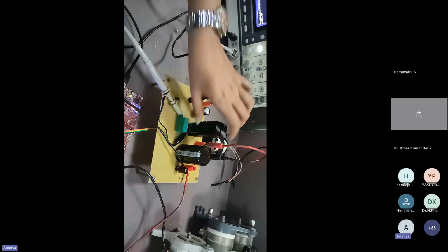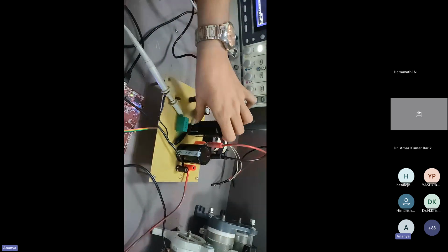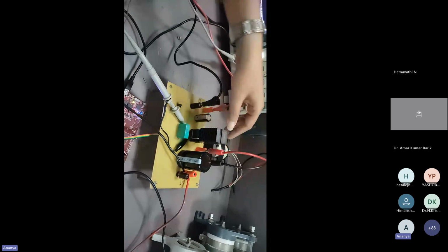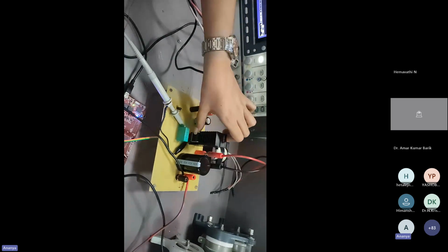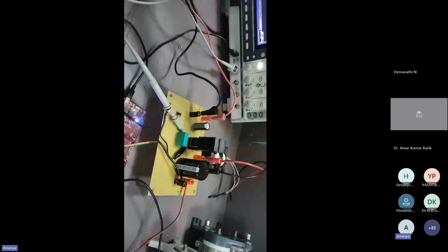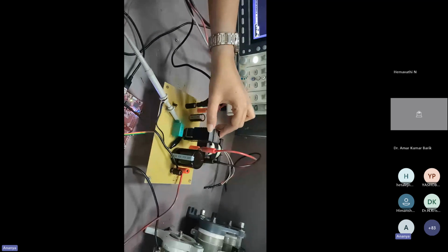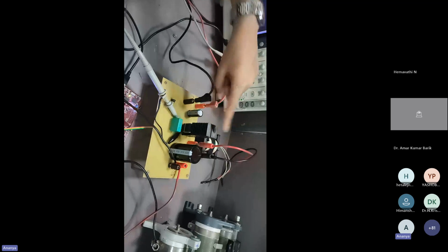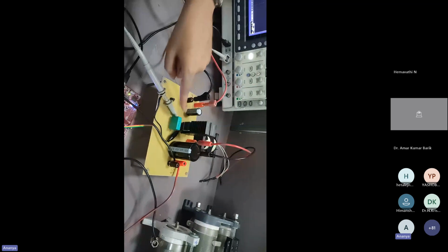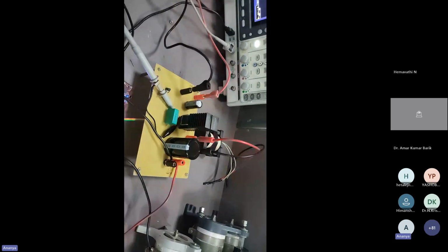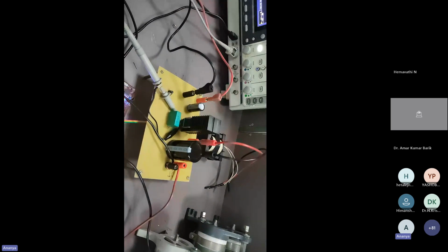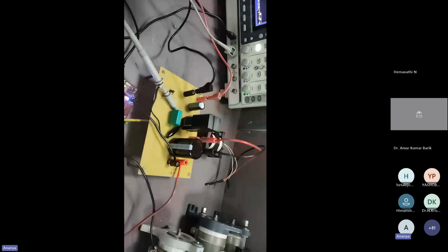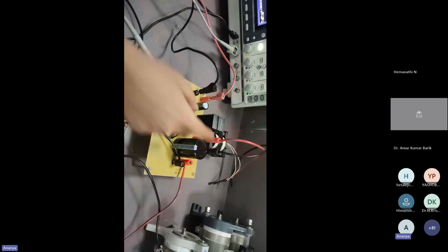This is our switch. This is from Infineon and it is rated at 65 ampere. This is the heat sink associated with the switch so that it can absorb the extra heat, for protection of the switch. The protection devices are the heat sink and the snubber. The snubber is basically to absorb any sudden rise in surge voltage across the switch for protecting the switch.